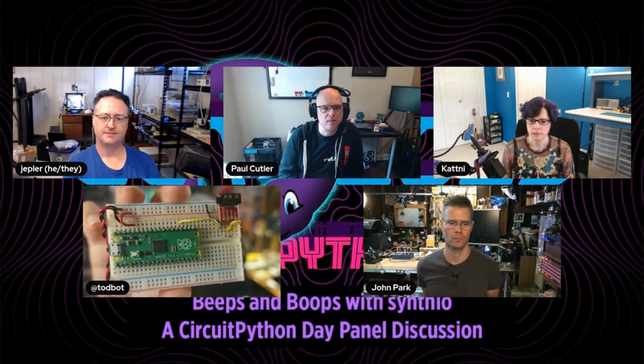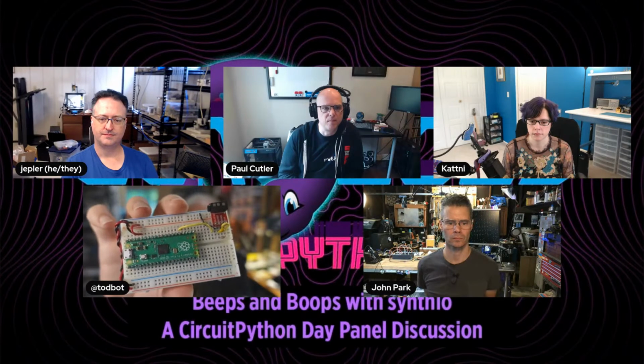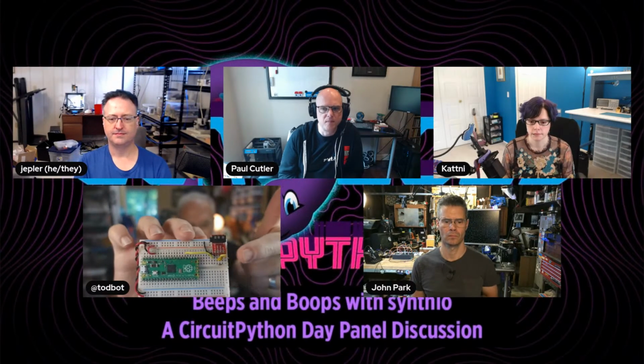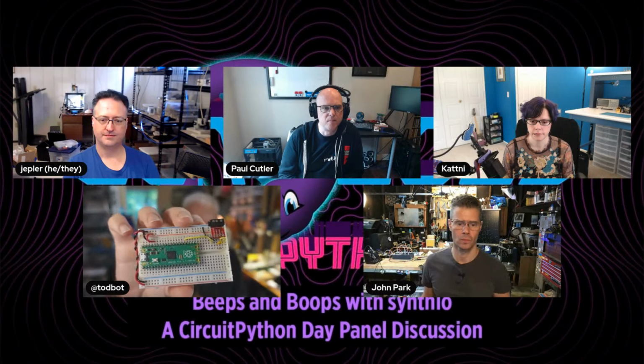So speaking of the ESP32 chips, this is a question I think for Todd. I was looking at a lot of the sample code that you've posted. You use audio PWM IO in a lot of the code, which is available on the RP2040, but not the ESP32 family of chips. Is there an advantage to using audio PWM IO? Only that it's very, very simple. Like here's the entire get started with synthio circuit that I use all the time, and it is a Raspberry Pi Pico and a little SparkFun breakout board for the 1/8" jack to your speakers, and then a resistor and a capacitor and a couple of wires, and that's kind of cheap and super repeatable.